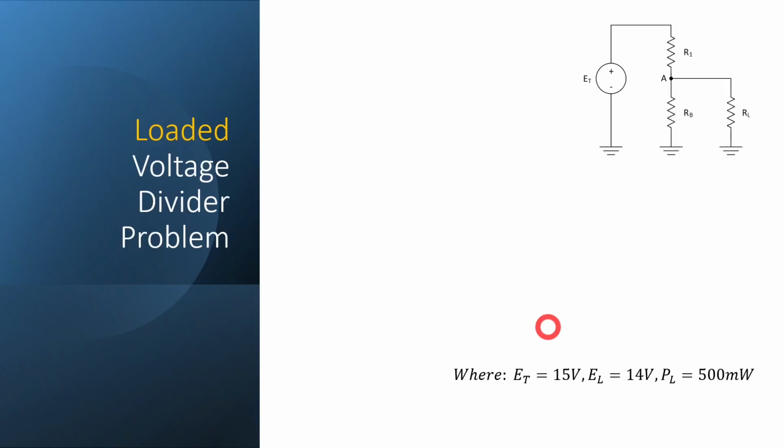Okay? Let's see if we can figure out the different wattage size to get. We're going to just do it for the bleeder resistor here, but the same principle is going to apply for all resistors in our voltage divider. So first we're just going to figure out our powers. So the P1 is going to equal the total current times our voltage drop across that R1. And so our total current times that 1 volt is going to get us 39.683 milliwatts.